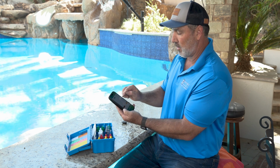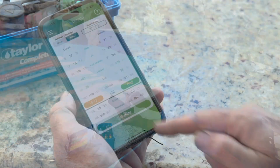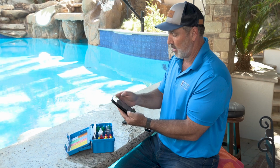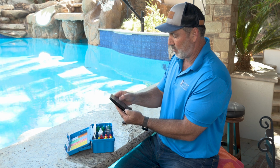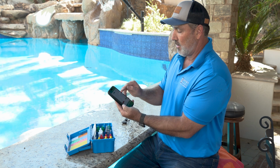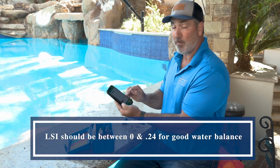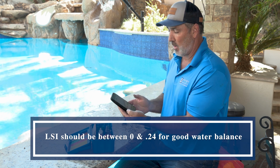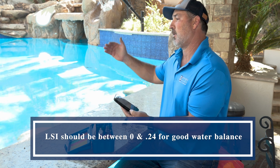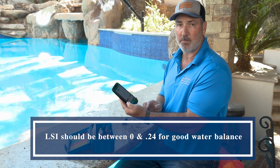So immediately, as I start to increase the pH from 7.2 to 7.5, my LSI goes to a negative 0.17, and you can see it's in the yellow. We're going to take the pH up to 7.6 and 7.7. Let's see what it does. So just by taking my pH up to 7.7, I've got an LSI of 0.02. So all I have to do to get my water in compliance, my pH is just too low. I need to increase my pH to 7.7, and my water chemistry is perfect.